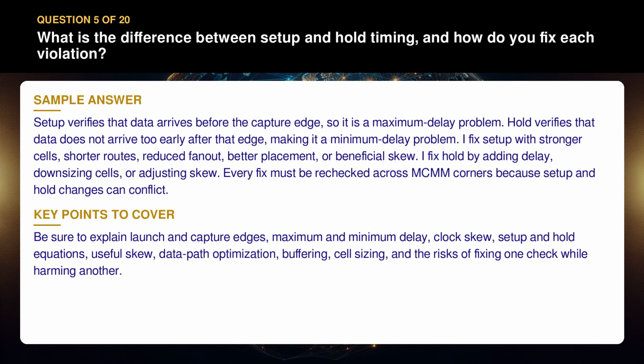Be sure to explain launch and capture edges, maximum and minimum delay, clock skew, setup and hold equations, useful skew, data path optimization, buffering, cell sizing, and the risks of fixing one check while harming another.